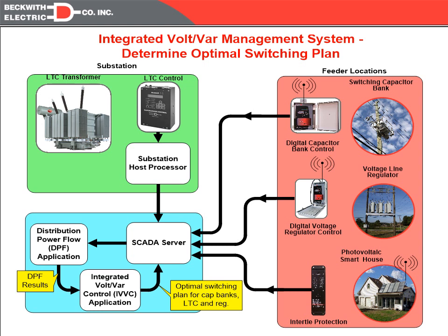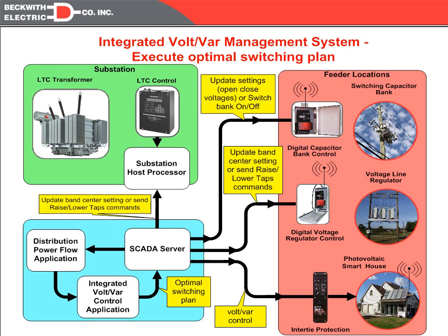Once that decision is made, the IVVC application will then send commands, and then it'll be up to the SCADA Master to then send those commands out to the individual controls. So that's the overall philosophy, whether it's a substation approach or a central approach. We're going to collect real-time data. We're going to do some analysis on that data. We're then going to direct SCADA to send commands out to individual devices to correct any problems that may be on the system.